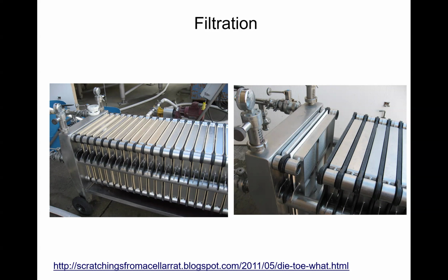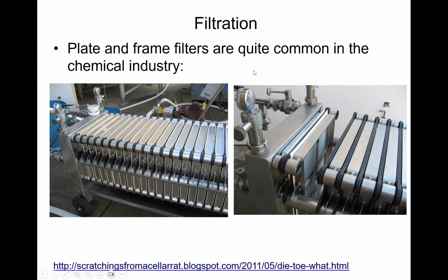In the setup that we are showing here right now is what we call a plate and frame filter. They're very common in the chemical industry. It is essentially a bunch of filters. So you can see this white filter right here, and it's basically sandwiched with a frame that holds it in place. Liquid will come through these tubes and then get into each one of these filters, and then eventually will leave through the other side.